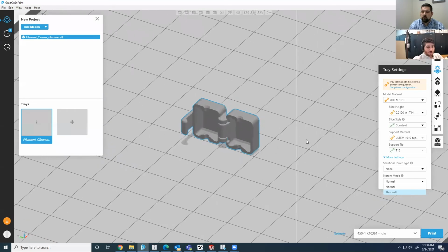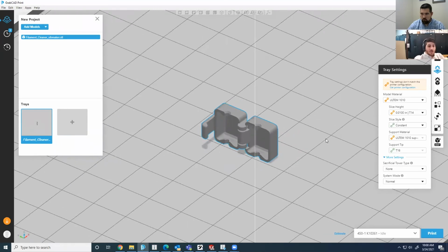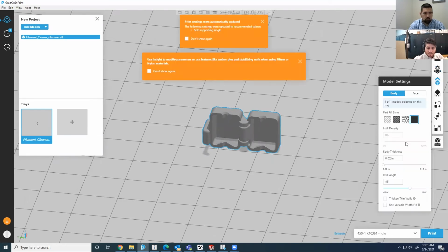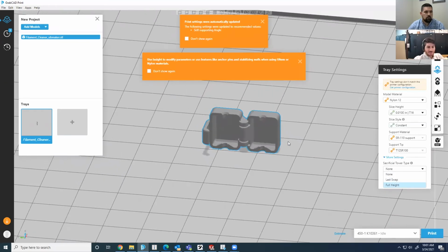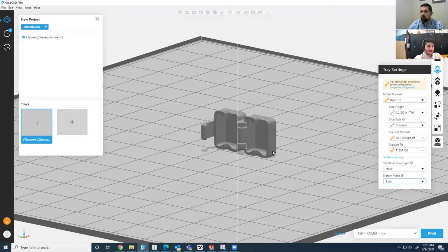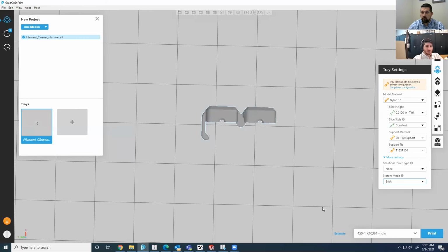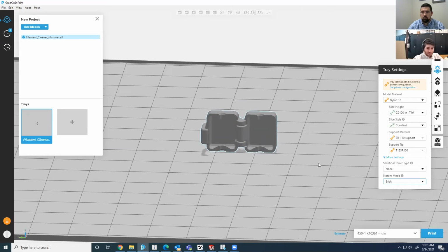With Ultem, you only have normal mode and thin wall mode, so it'll decrease the oven temperature, I believe, by 10 degrees Celsius. With nylon material, you have a brick mode. So if your part is thicker than 1/2 of an inch, your thinnest feature is greater than 1/2 of an inch, then you want to use what is called brick mode. This will increase the oven temperature and decrease curling of the parts so that it is at the correct cooling temperature for the parts to gradually cool down and get their correct geometries or shape sizing after they shrink.